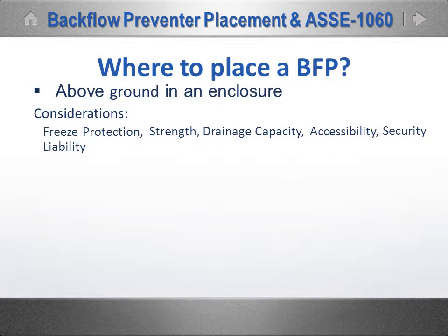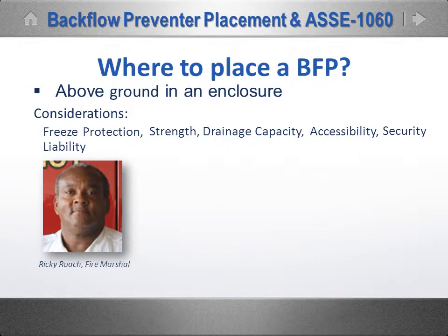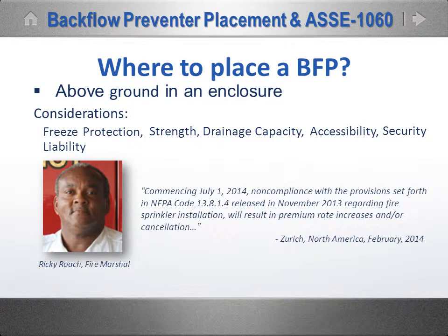Speaking of insurance policies, Ricky Roach is the fire marshal of Waycross, Georgia. He recently got a letter from the city's casualty and liability carrier, Zurich North America, stating that commencing July 1, 2014, noncompliance with the provisions set forth in NFPA Code 13.8.1.4, released in November 2013, just a few months ago, regarding fire sprinkler installation will result in premium rate increases and/or cancellation. So you understand what this code refers to.